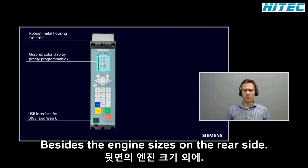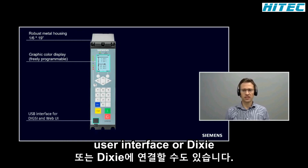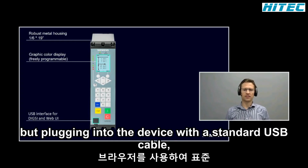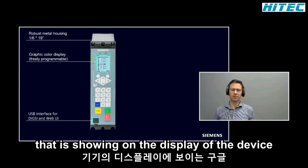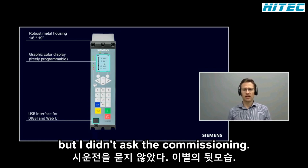Besides the interfaces on the rear side, you can also connect to the web user interface or DIGSI via the USB front port. You can do this by plugging into the device with a standard USB cable, using any browser such as Internet Explorer or Google Chrome. The LED labels are shown on the display of the device, simply by pressing the LED description button. The advantage here is there are no ugly paper strips needed to be printed and slotted in after commissioning.